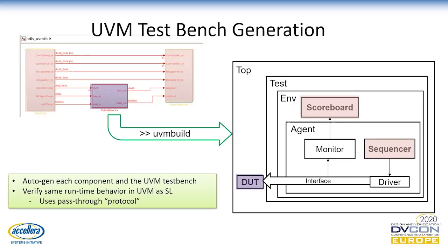It's a kind of complex environment. So we can provide you the skeleton on which you can hang or expand your functionalities, for the scoreboard and sequencer and driver, etc., and to connect it to the DUT and the monitor and all that. So that's basically done by us for your benefit.